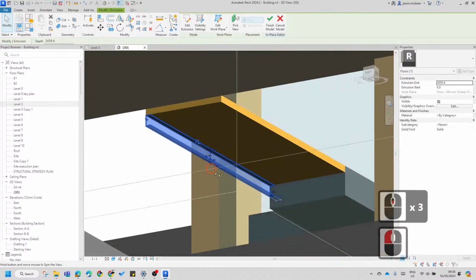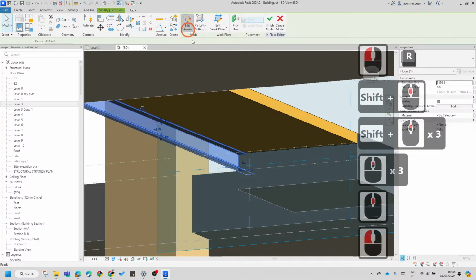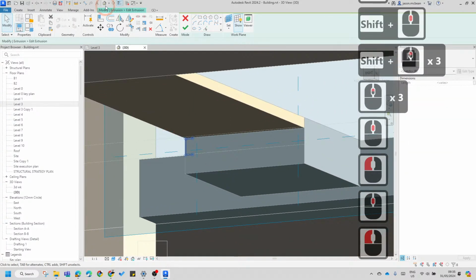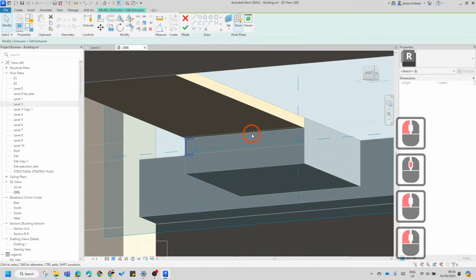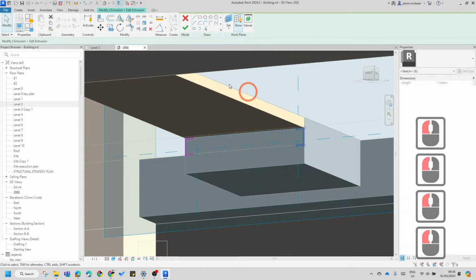Okay, anyway, what's neat is, say now I want the steels going in both directions. So I'm going to say edit extrusion. Guess what? I'm going to grab that. I'm going to use the mirror tool. Mirror by center line.